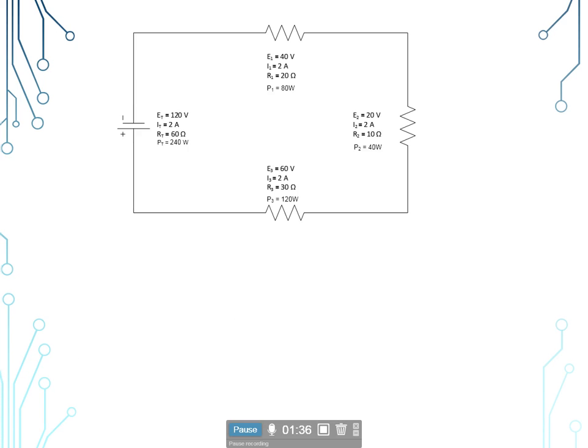This is a schematic, a wiring schematic, our map of how to wire something. And a few little things about it. This symbol right here, that is the battery symbol. It is a cell symbol actually, which is the smallest component of a battery. We use the cell rather than linking multiple cells together just to save some real estate. The long bar on a cell is always the positive, the short bar is always the negative.